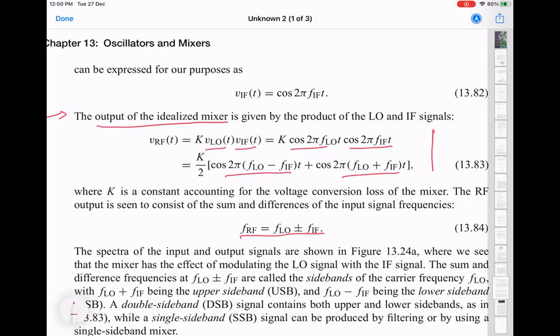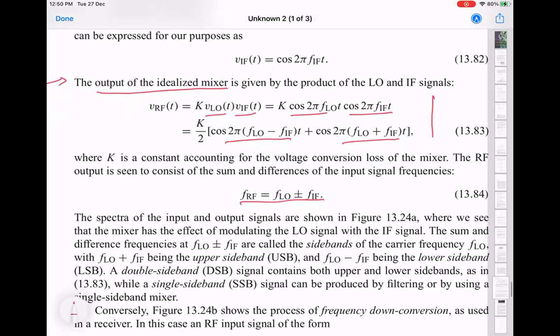So again, nomenclature I mentioned, LO plus IF is called the upper sideband, the LO minus IF is called the lower sideband. Yeah, LO should have a very narrow bandwidth. Right? So LO is by definition, in the ideal case, like a delta function. So in a real setup, the line width of that will depend on what source you're using, but ideally it has a very, very sharp narrow line. So it's like your laser in an optical system, if you want to think about that. So microwave sources can generate signals which are very, very narrow in band. So that is sort of a given.